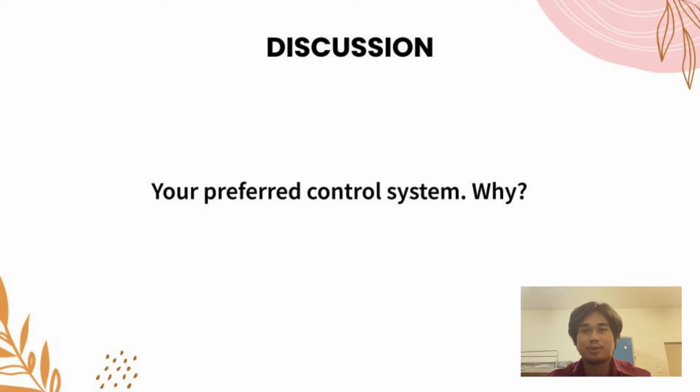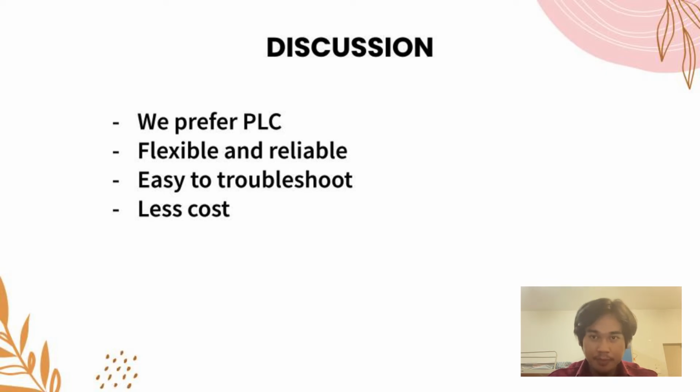After conducting this project, we managed to complete both the electrical wiring and PLC wiring of both the DOL starter and the forward reverse starter. And you notice many differences between the presence of PLC and without PLC. Both control systems are very different but perform the same function, but based on our personal preference, the majority of us prefer a control system with the assistance of PLC. This is due to the fact that the PLC is more flexible and has better reliability compared to the conventional one. The PLC doesn't consume many wires since we don't use a relay-based control system.